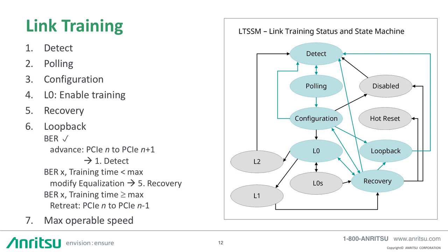In the context of transmitter equalization testing, a BERT error detector plays the role of reference receiver operating in loopback mode. It directs the BERT pulse pattern generator, I'll call it a pattern generator most of the time today, to send requests for different presets to the SerDes device under test transmitter. An oscilloscope captures and analyzes all of the transmitted waveforms.